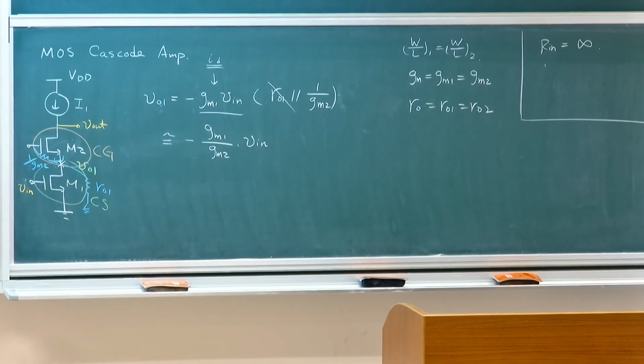Okay? So one of the key points is that because of the low input resistance of the common gate stage, you will not see amplification of voltage at this particular point. The magnitude of the voltage is almost the same, identical if I have the same GM, meaning that it does not do voltage amplification across these two terminals.